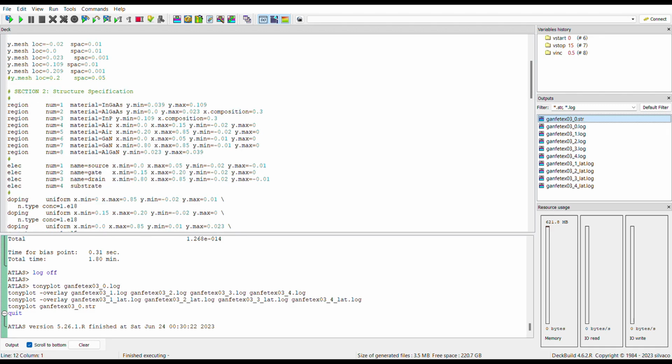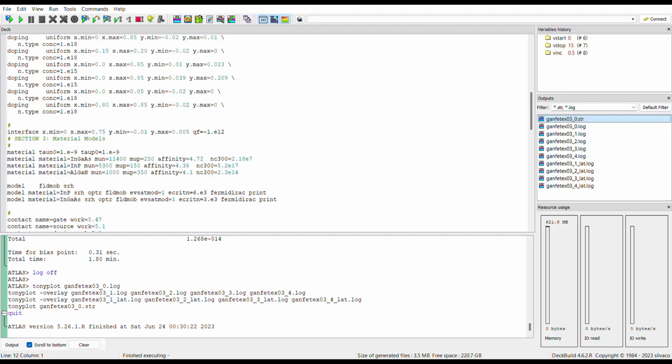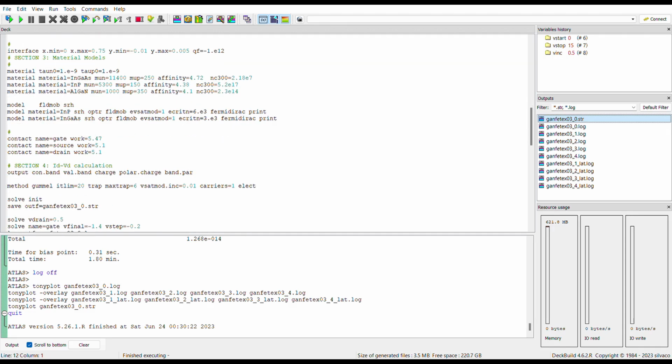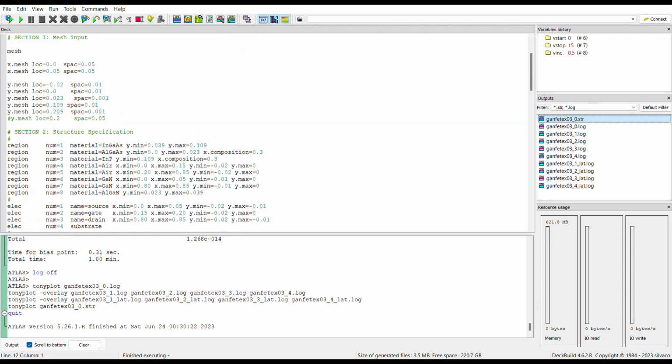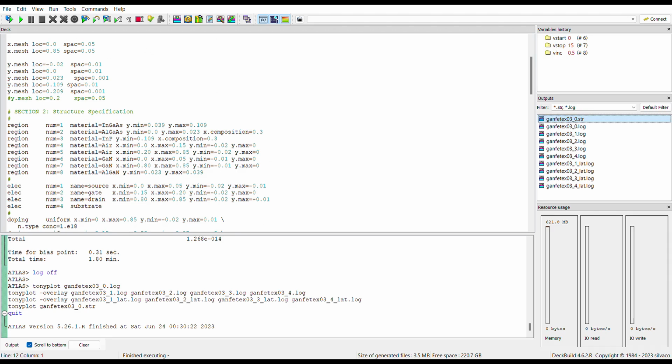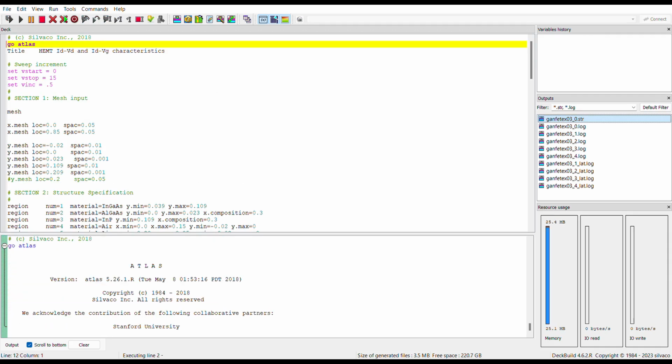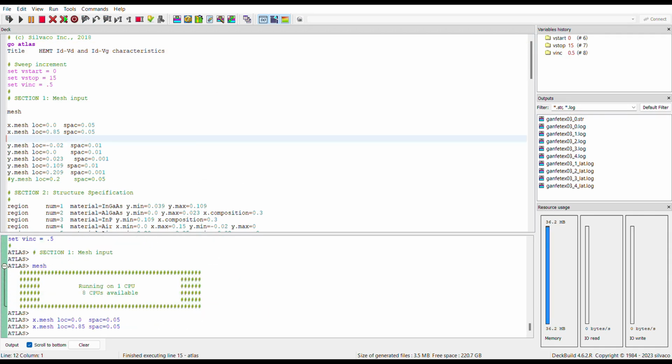We have also reduced the length of the electrodes to 0.01 mm for source and drain and 0.02 mm for gate. We also changed the work function to copper on source and drain and gold on gate, as you can see in the code. So this is our overall code. Now if we run the code, it will take some time to compile.